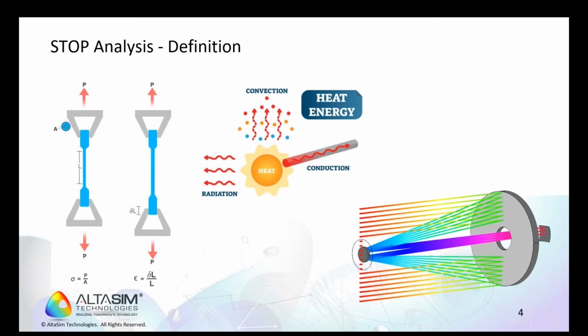So the structural analysis assesses how the mechanical and thermal loads deform the system. The thermal analysis calculates the temperatures within the system, and then this temperature data could be provided for the thermal loads in the structural analysis, and then also to the optical analysis for temperature-dependent material properties. And then the optical analysis combines all that information, the structural deformation and the temperatures, to calculate what the optical performance of the deformed system looks like.